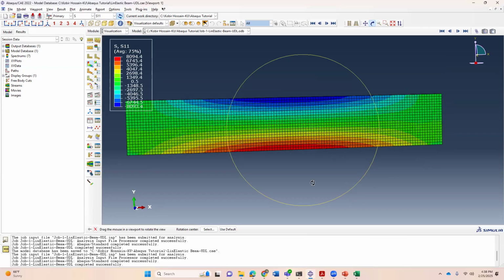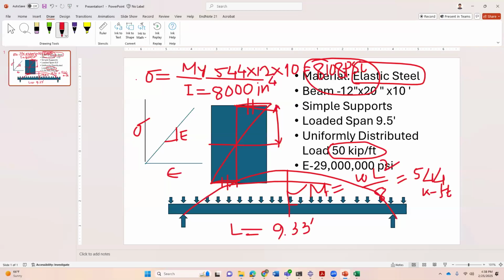Now let's get the displacement. So for this beam, the maximum deflection will be in the mid span, right? This beam will bend like this, say, under this load. By how much, we don't know. But the maximum displacement at mid span will be this much, and that can be calculated, delta max, as we know the formula for a uniformly distributed loaded simply supported beam.